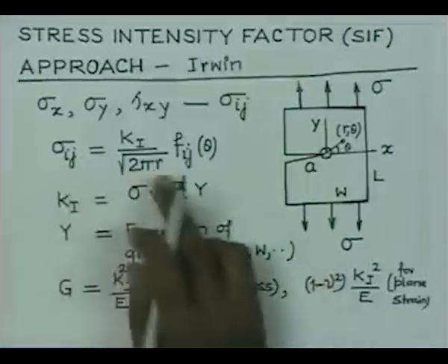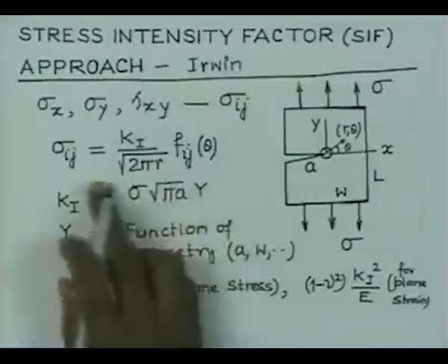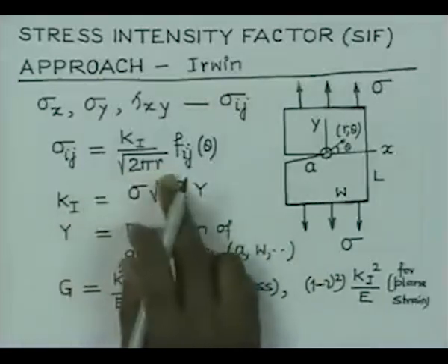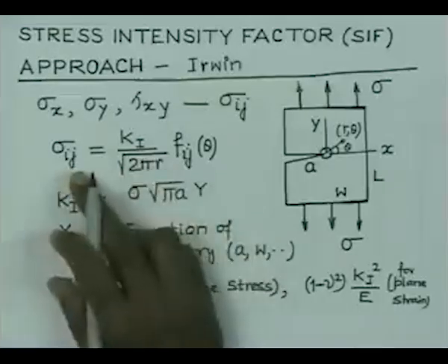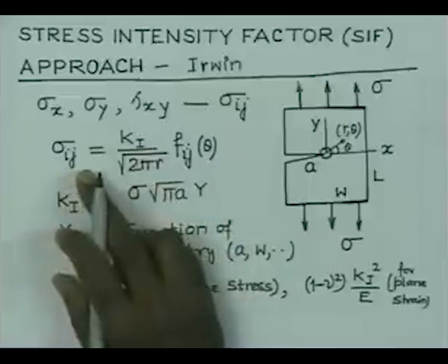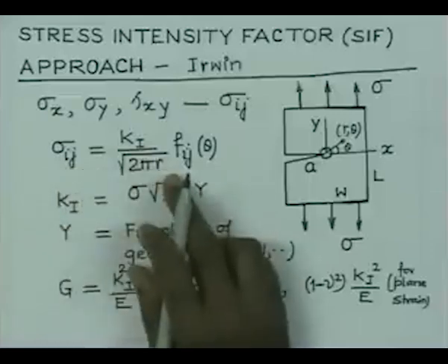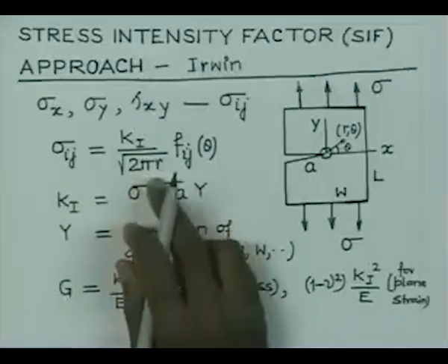So, there is a singularity in the stress field: as r tends to 0, stresses shoot to infinity. This is considered to be a stress singularity, and the order of the stress singularity is considered to be a square root singularity.